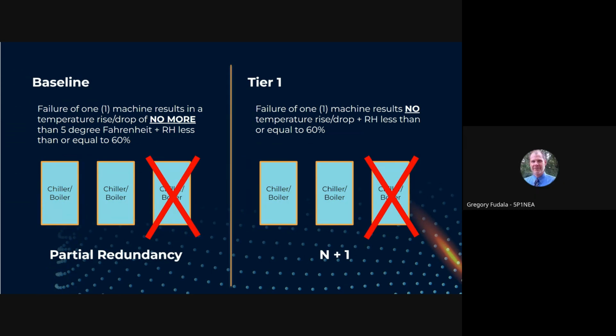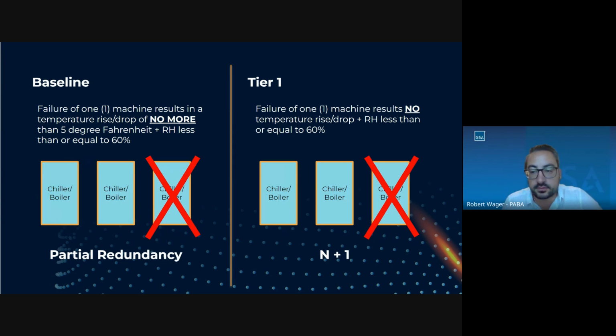Yeah, Bobby, when you have different sized chillers in your plant, do you just default to the largest chiller? So how would that work? Greg, I'm going to get ahead of that real quick. You shouldn't have different sized chillers in your plant. P100 still requires you to have equally sized machines. So the thinking is your machines are equally sized, and if you were to lose one, your other 2 equally sized machines would be picking up this load. So we're not deviating from equally sized or mismatched sized or pony chillers or any of that nature. We're still holding that requirement of equally sized machines.